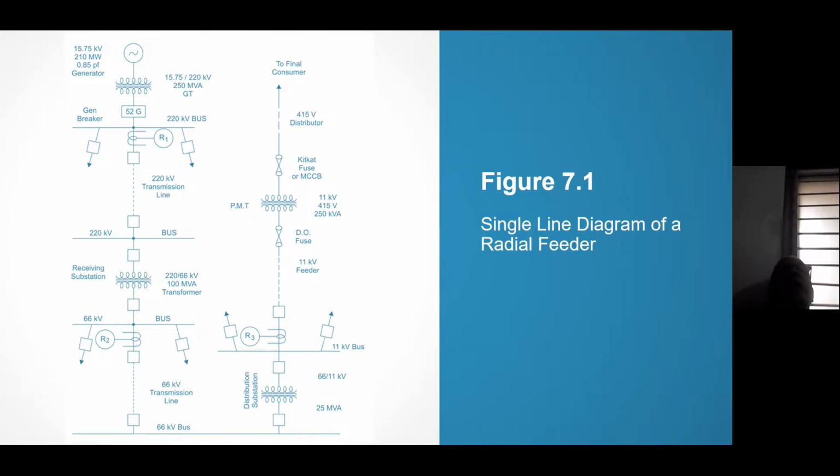We have seen relay backup in generator protection, generator reverse power protection. We are using 3 relays, 2 low forward power and 1 reverse power, because it is very important. So there is triplication of relays, and not only relays, the CT core feeding the relay is also different. So we are spending a lot, because we are protecting some 1100 crores of rupees of transformer. Here the cost is not that much.